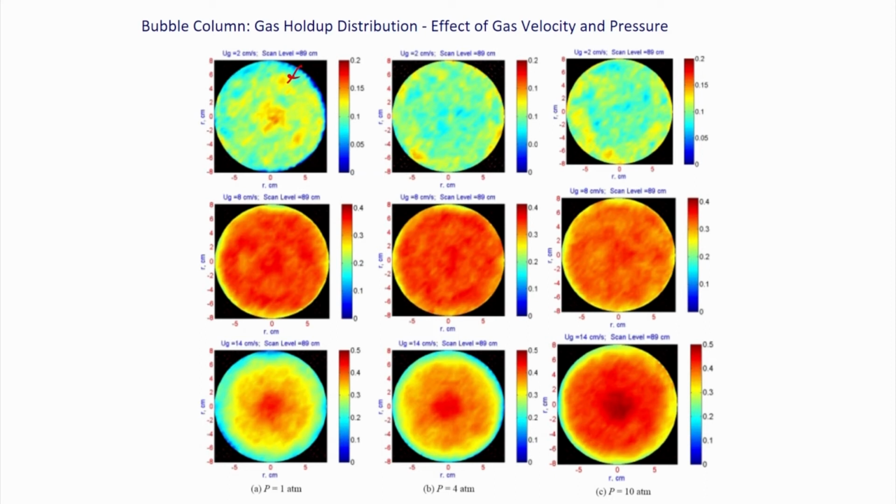So, that is the beauty of this. If you see the spatial resolution, it is very good compared to EIT or ECT. The only problem is the temporal resolution, which is not that good because your experimental time is very high, and that is the major area of work which one needs to do in the measurement technique to develop a gamma ray tomography, where the temporal resolution of that tomography technique is very high.